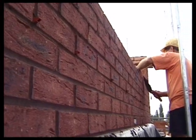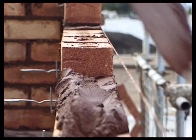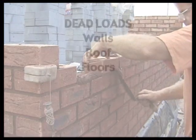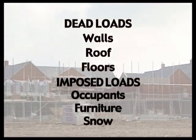Foundations must carry the loads of the building and transmit them safely into the ground. Any settlement must be sufficiently controlled to minimise building distortion and cracking. The load of the walls, roof and floors are known as the dead load. The loads of the occupants, furniture and snow are known as the imposed load.